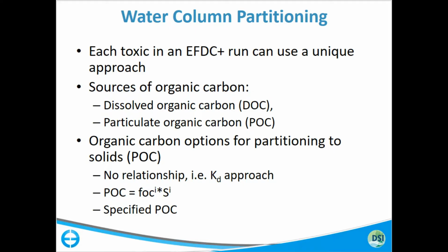The second approach is if you ignore organic carbon, you essentially end up with KD. If you don't ignore it, then you have to specify the fraction of organic carbon for each size class in the water column and in the sediment bed.